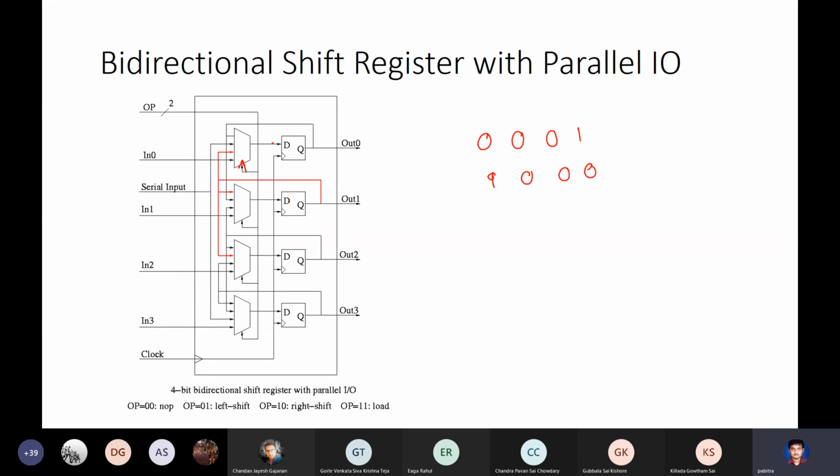So there are 4 input lines, because every shift is just a movement here or a leading 0 coming in here. Accordingly, this can be obtained by the previous input, so you ask the multiplexer to forward the corresponding element, and then the D flip-flop, as you know, will just transfer it in the next cycle.